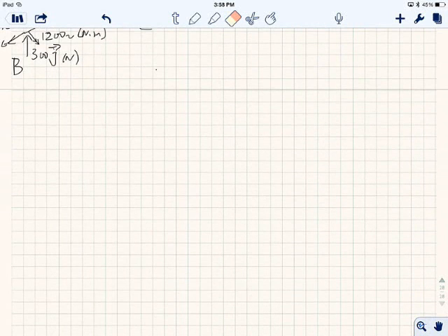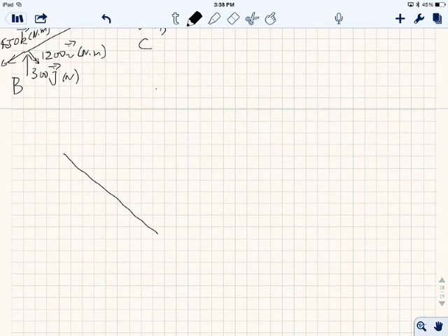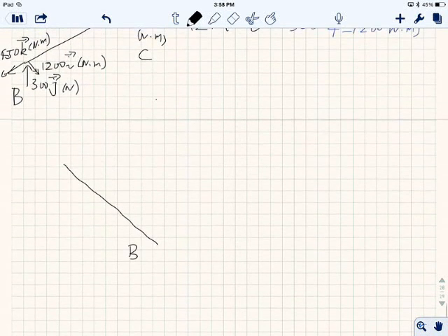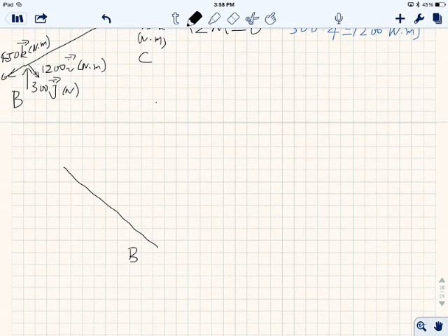Okay, so lastly, let's look at AB. Okay, now AB, first of all, point B. Now, like you see over here, this B has three different components. You have a force going upwards in the direction of J. You have a torque equal to 450 in the positive K. You have bending moment of 1200 I, Newton times meter, right? So three components at point B. At the same time, point B is also on AB, so you use Newton's third law. Everything should be inverse in direction, but same magnitude to balance for the internal component of B over here, right? So automatically I know on point B, on the member of AB, you'll have a force